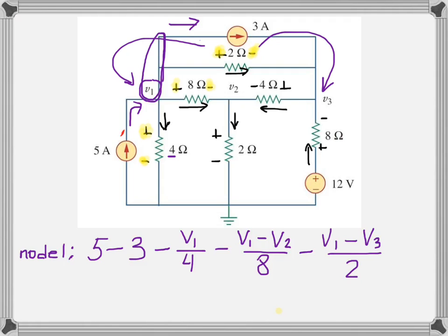So now it looks like we completed the equation, but let's double check that we included all currents, so we didn't miss anything. Let's count the number of branches connected to the same node, node 1. It is 1, 2, 3, 4, and 5. So we have 5 branches.